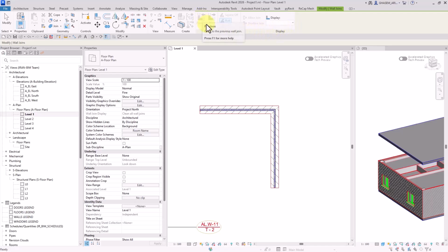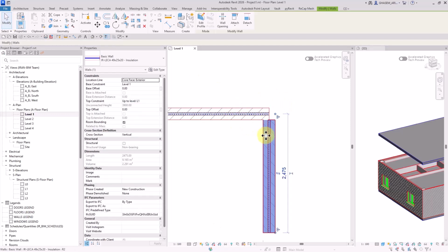Now, we can, for example, select this corner here, then up here select a joining condition, and then we can select one of these structural designs that we have for the joints. And if we didn't want the walls to be joined, we can just easily use this item to disjoin everything. And obviously we are able to join everything once again using this one. Yeah, so all the sub-items are set in the ribbon now, and we can easily use them. Let me join these.